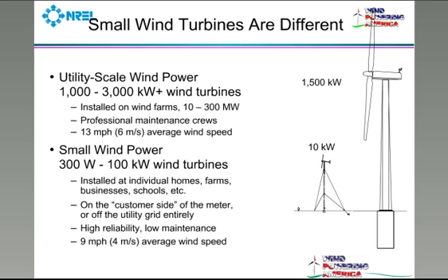And they're more designed for low wind speed regimes where the majority of the loads are. You can get a decent amount of production going as low as 4 meters per second, so about 9 miles an hour. Although at that low, it probably only makes sense for an off-grid application where you're comparing it against, say, a grid extension. For an on-grid application, I like to see 4.5 meters per second, or 5 meters per second, somewhere in the 10 to 11 mile per hour range before it gets really interesting.